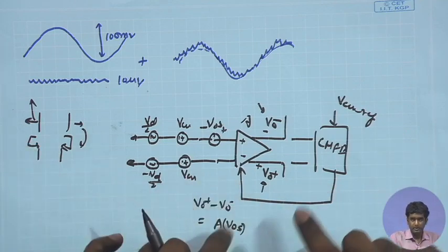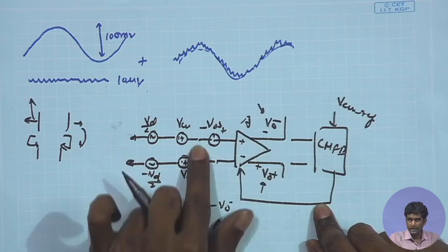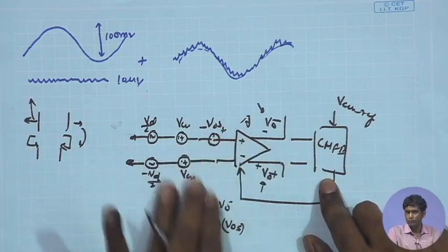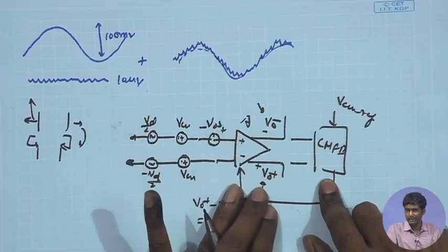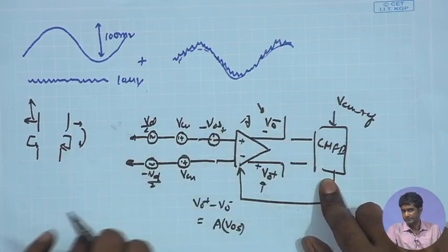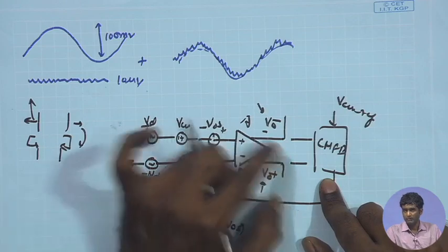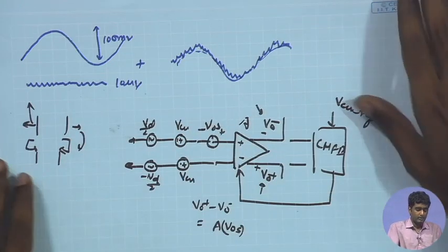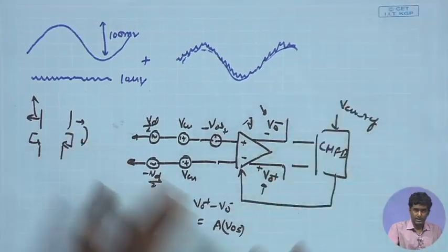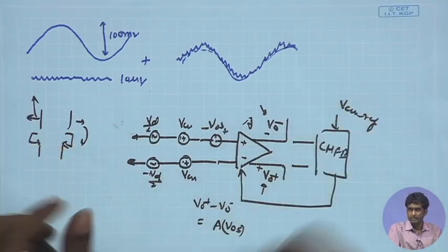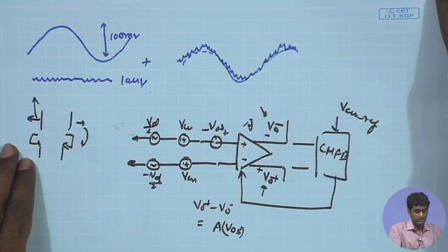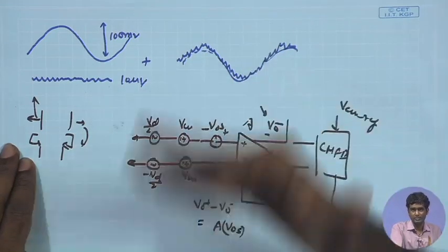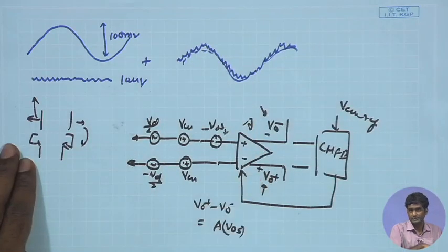Therefore, independent control of the output common mode and input common mode can create these issues, and if we do that, once again we may have to go for auto zeroing and those kind of techniques to take care of this offset voltage, so that the offset is compensated and we are able to cancel it out. But once again, if you apply auto zeroing in the front end amplifier itself, and you have so much switching noise coming from those transistors, they can once again aggravate the noise considerations. They can make the noise worse.